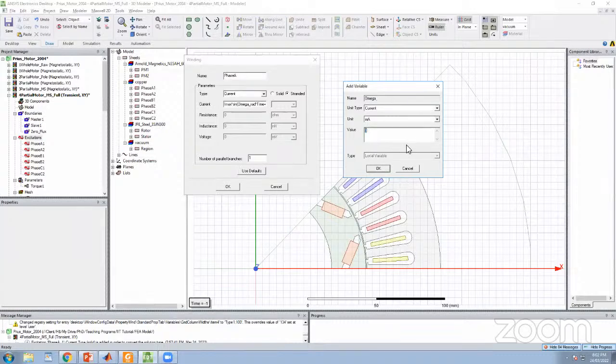What's omega? Again, we need to calculate omega from the speed of the machine, which is the speed in RPM times pole pairs divided by 60 times 360 degree, right? These should not have unit. Okay, omega and motor speed.